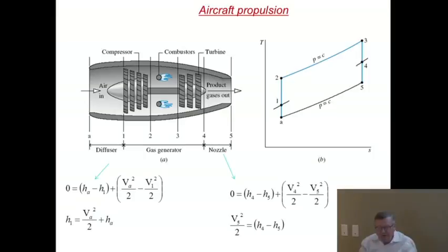Let's move to another section. These turbines, as we have seen them, mostly are highly optimized for efficiency, and they're mostly used, therefore, for power generation. If you were to look at propulsion, then the equation is entirely different. So what you really want in propulsion is a maximum amount of power in as lightweight, as small an engine as possible. And then, of course, you still want to have efficiency, but you want the efficiency without weight. Weight is a new added penalty. Weight and size are two new added penalties for aircraft propulsion.